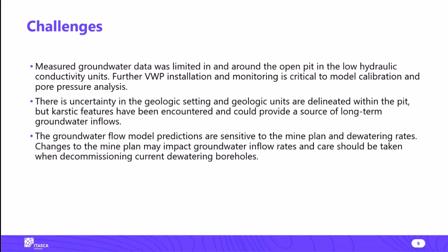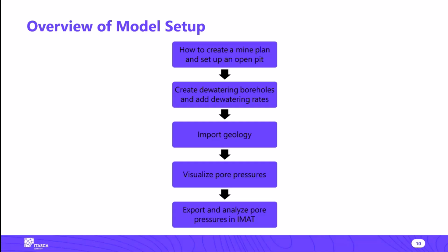Highly permeable features also provide challenges as they are conduits of high hydraulic conductivity and groundwater flow into the open pit. As a part of the analysis, ITASCA provided an assessment of the model uncertainty and potential range of dewatering requirements and depressurization for future mining.